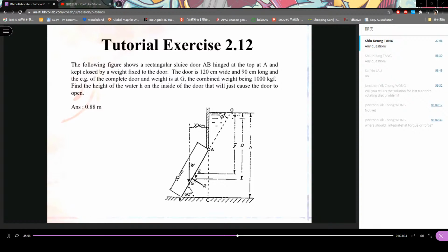So what we are going to do is to find P(x). So M equals 0, integrate to L, which equals 90 cm, of pressure P(x) times W dx. So what is pressure P(x)? Hydrostatic equation, right? Now, we have atmospheric pressure at this point, and we have atmospheric pressure on the other side of the door. So in this case, we just need to take into account the gauge pressure.